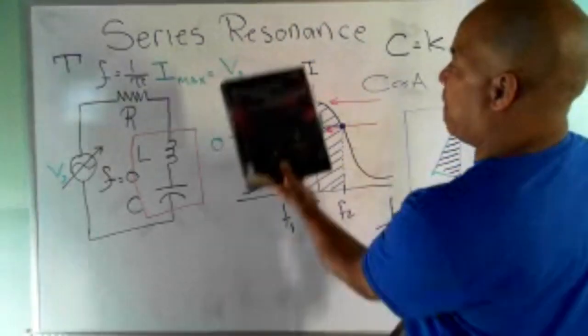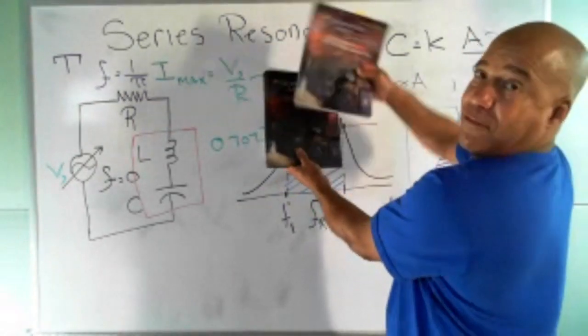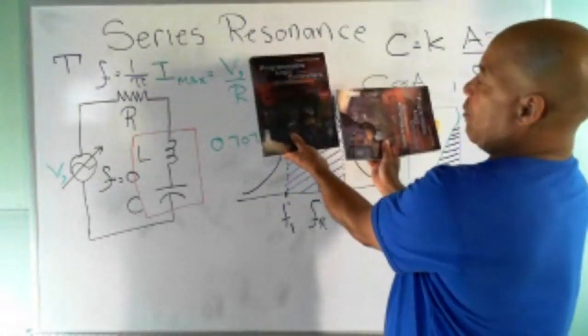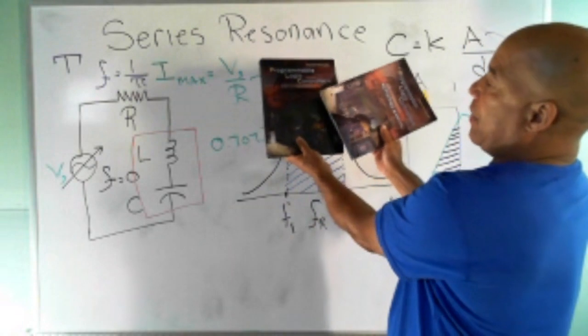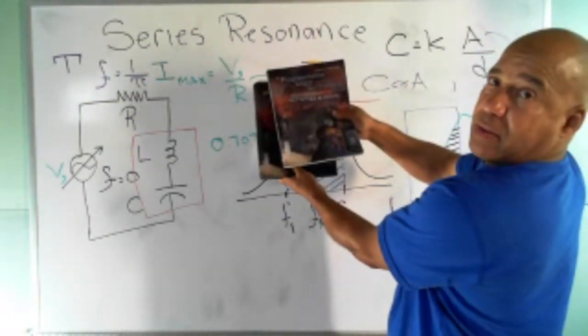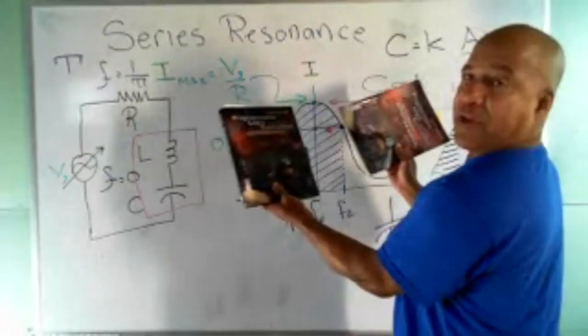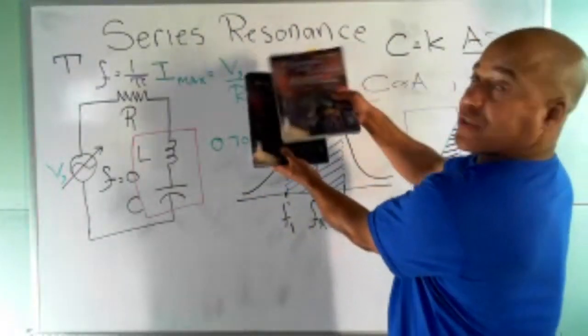So imagine now I have a fixed piece of metal, and I have another one on a hinge that I can move back and forth like this. I can have it over here, and I can turn the knob, and I have more and more mutual area until I'm like that, I have the whole area, if you follow what I'm doing. That's a variable capacitor. I just designed for you in front of your eyes a variable capacitor.